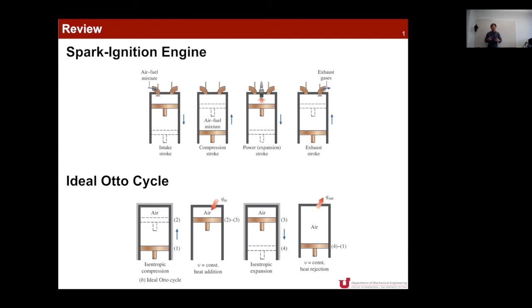That is so intense that it pushes the piston back to the bottom. That is the expansion stroke. After completion of the expansion stroke, all the burned gas should get exhausted. So the last stroke is the exhaust stroke, where the piston moves up to expel all the burned gas out of your engine. So you have to remember that this engine has 4 strokes as one cycle.